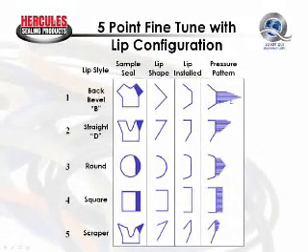You can see that the B lip has a greater amount of radial force exerted against the sealing surface than the D lip. And the D lip a greater amount than the round lip, a greater amount than the square lip, a greater amount than the scraper type lip. So the further these pressure patterns extend to the right, the better the conformity to the sealing surface under low or no pressure.